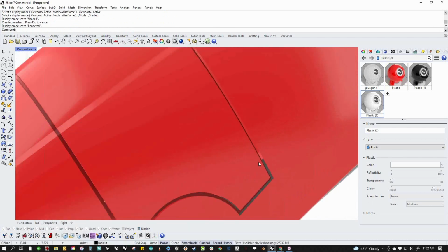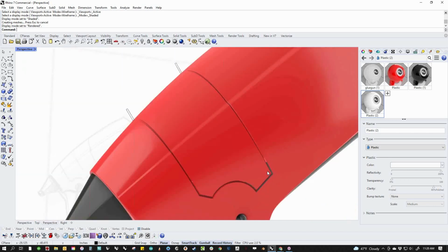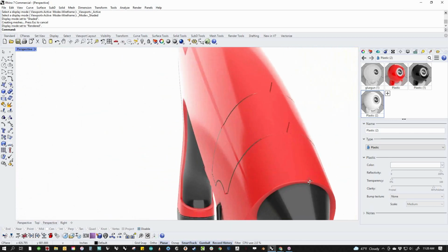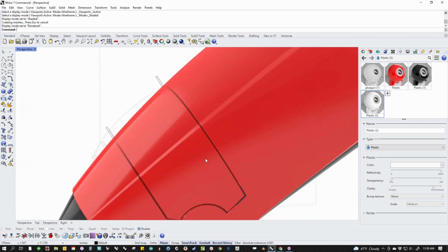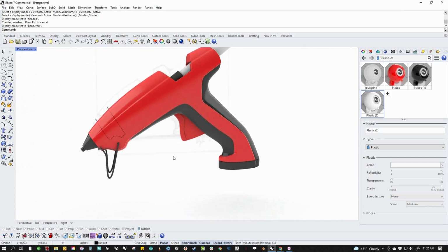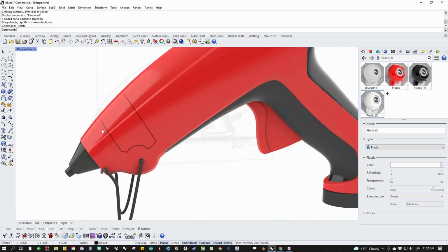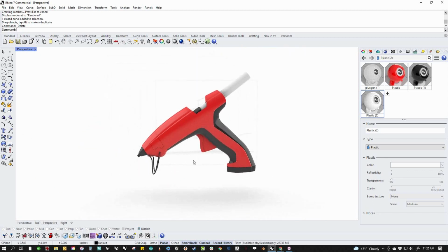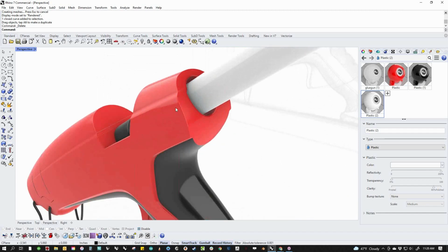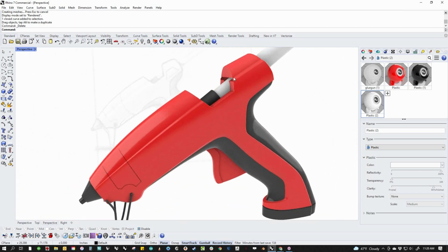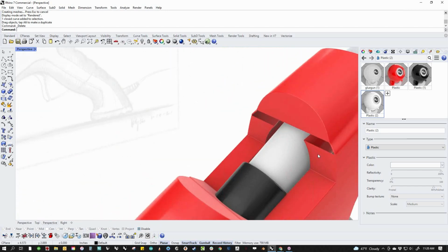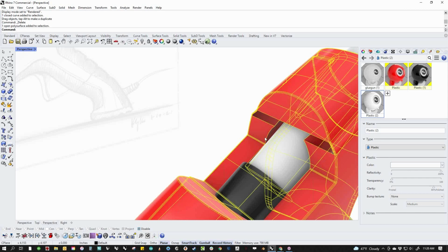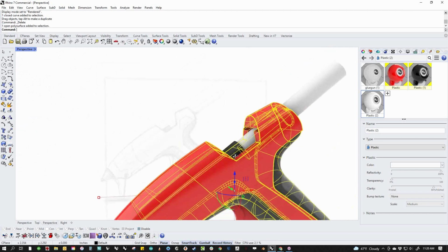If you needed to print this, I'd go in and connect all these little dots, basically connecting those surfaces. But if we were just doing a rendering or something like that, I might just leave it, call it a day. And that gives you a little detail. All right, so if we added a chord, I think we'd be done. If I had gone back and untrimmed this and cleaned this up, this would be a watertight part. In this case, it's not, but to clean it back up, it would simply be a matter of removing this surface and redoing it, and then redoing the Boolean.